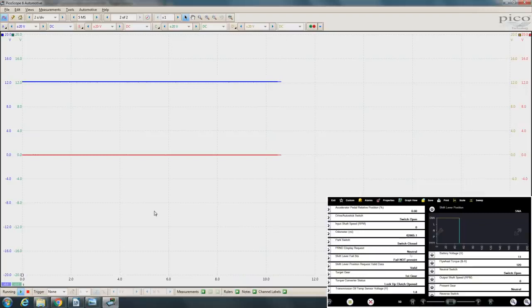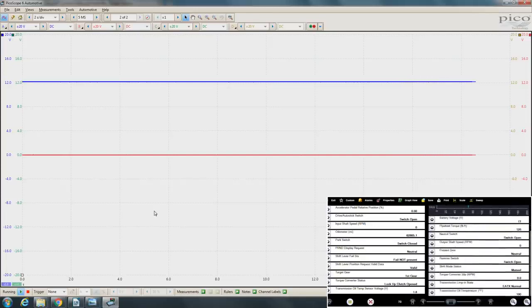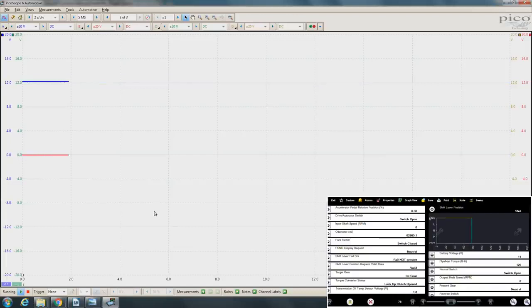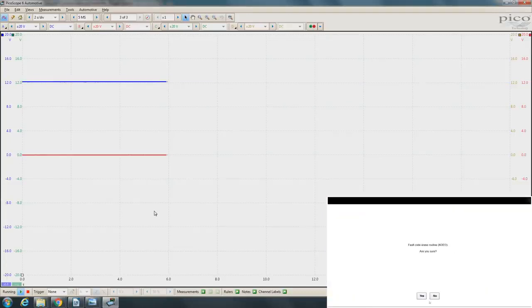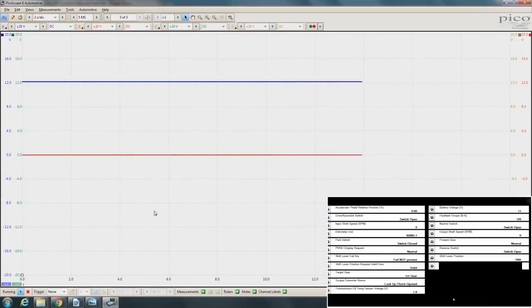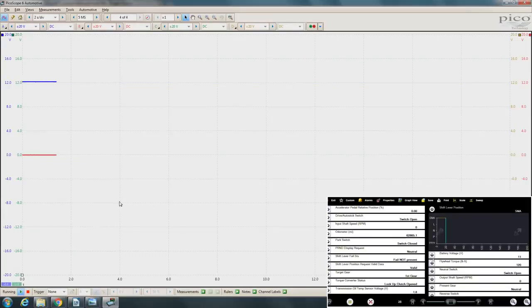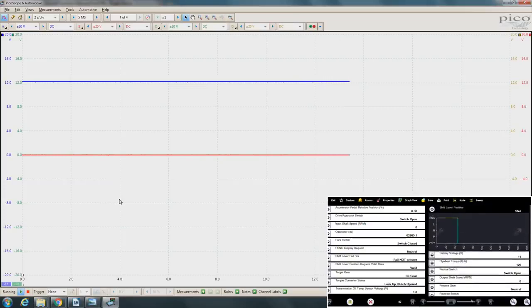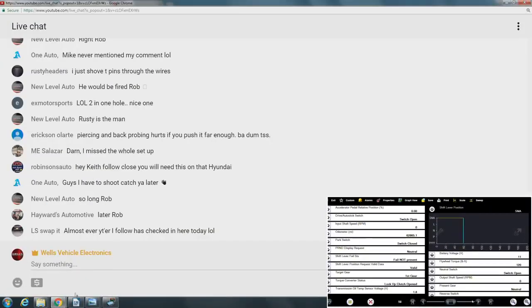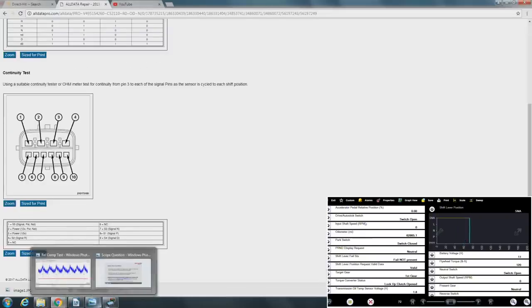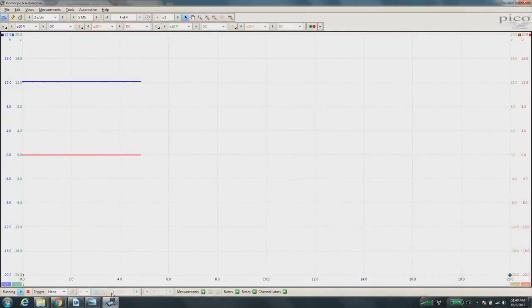Shift lever fail status, fail not present, park switch closed, transmission in neutral, present gear neutral, and you're in park right now, right? SNA. I wonder if that's because we unplugged it with the key on. All right, let's back out here. Let's just do a quick code clear. All right, I don't know what SNA means. That's interesting. I was assuming this should read park right now. We have the key on, right? Key on, we're in park. Okay. Well, anyways, let's go back to the scope because apparently the scan tool's not showing us what we want anyway. But go ahead and do the shift again.